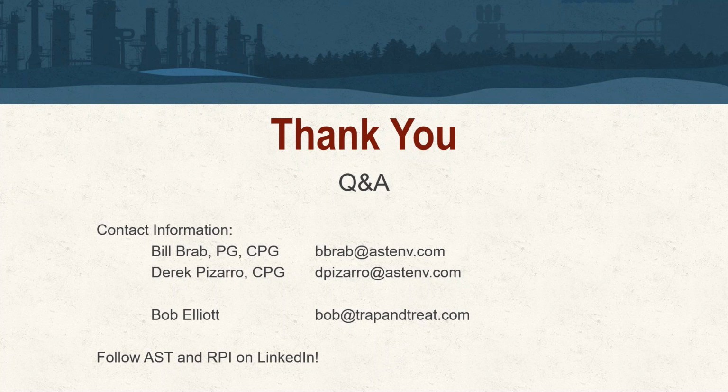When we get a weathered unit, we're going to use something we call pre-drill methodology, and that involves using augers or sonic rigs to reach the top of competent bedrock, stop at that interval, and then complete that borehole with hydrated bentonite pellets or chips. And then that bentonite column in that borehole allows us to go back through it with a DPT rig for injection. In some cases, we may use the bedrock truck, but we may not need to. So that's how we access that transitional or weathered zone.